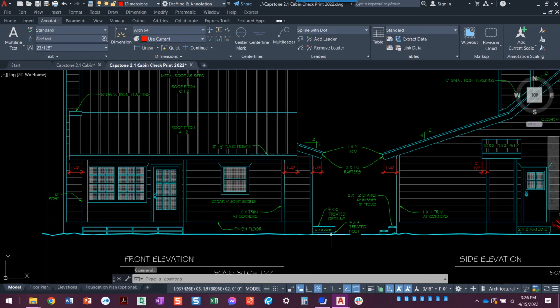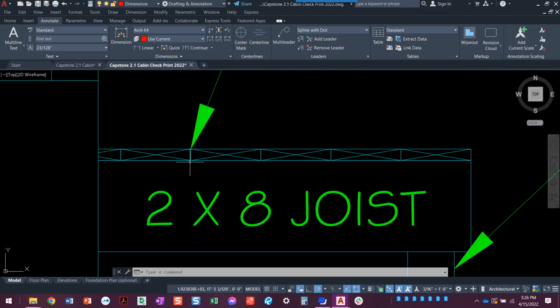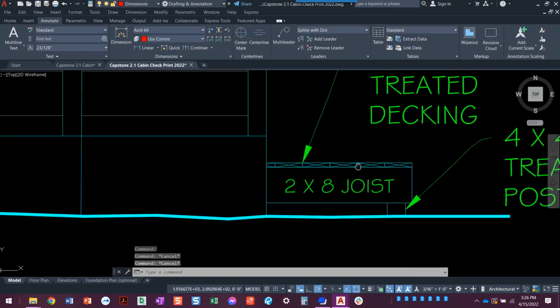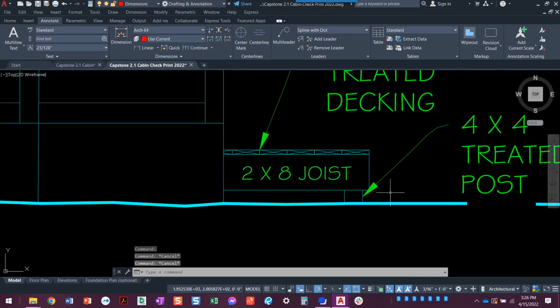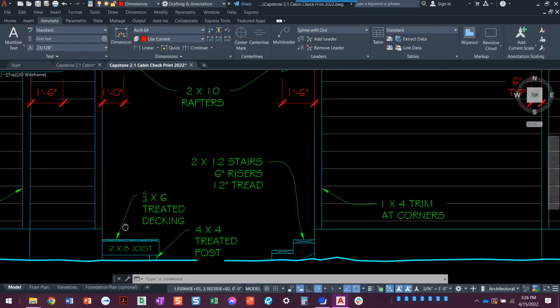Your final one is going to look like this. This is what I'm talking about. This is the part that you need to go in there and draw. And you can see that we did it just offsetting. Like from here, I actually drew in a 6-inch by 1 inch rectangle, put an X on it and then copied it, just so you could see the deck boards 8 inches down, and then that's the 4x4 post. So you do need to put that in there with the note.